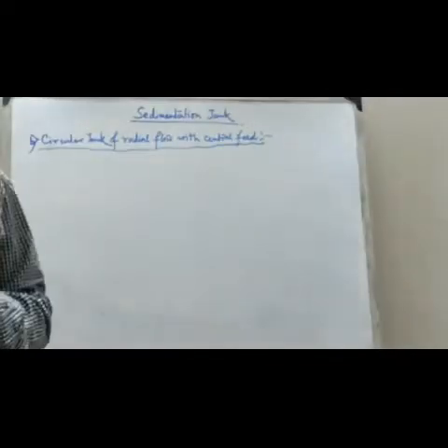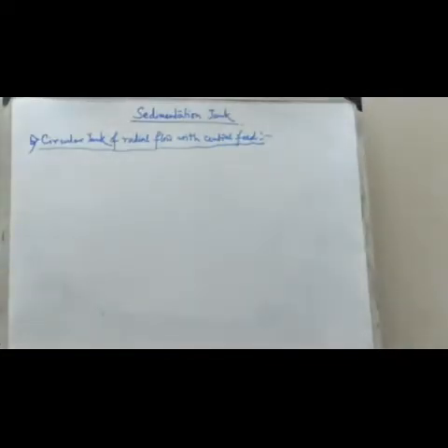This is another type of sedimentation tank, in which the water enters at the center of the tank into a circular well provided with multiple ports, from which the outflow is directed outwards equally in all directions, and thus flows horizontally and radially from the center towards the periphery of the circular tank.